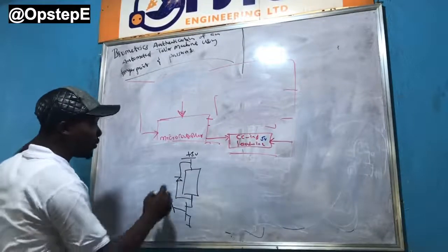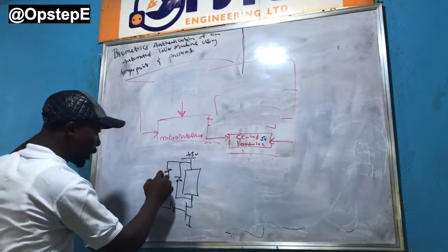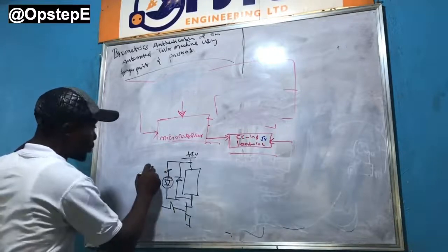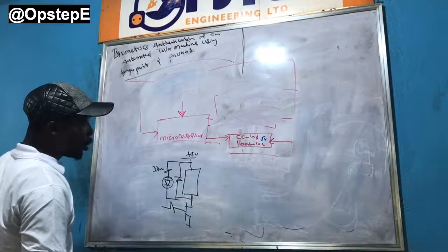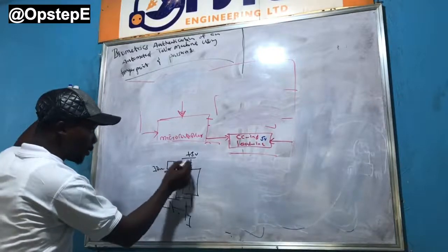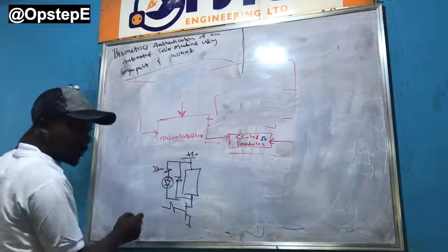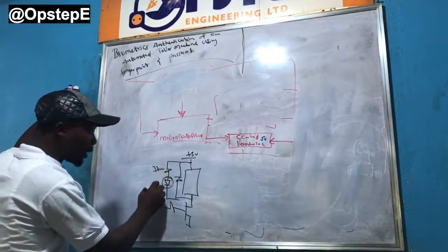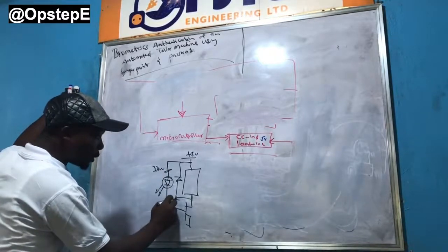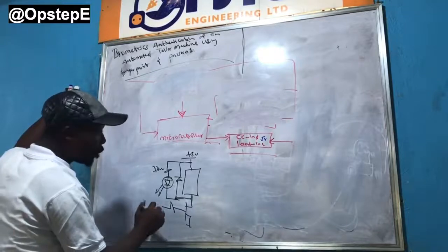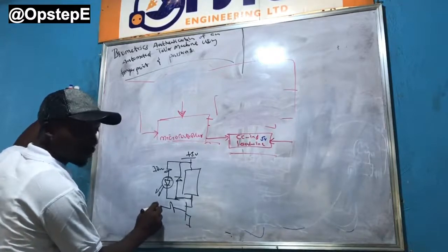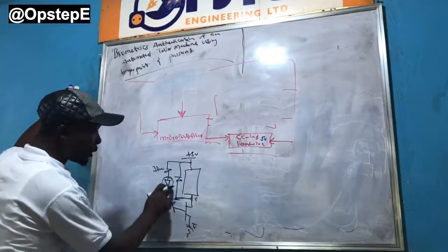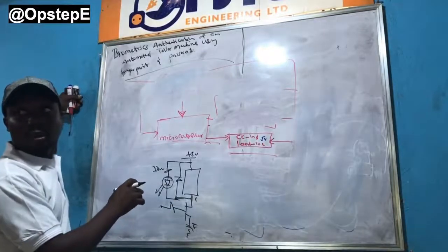Yeah. So what I would do is just have, from this end, a resistor to a light emitting diode. Now since this is 5 volts, the 330 ohms is fine here. Don't forget, this part of the resistor already has source, I mean there's signal there, and that signal already flows to the anode of this light emitting diode, isn't it? This light emitting diode is waiting for what? Negative. Are you with me? Yeah. So it is when the base of this transistor is biased that the collector comes to the emitter, which joins to ground. That's when this light emitting diode will come on. Does it make sense? Yeah.